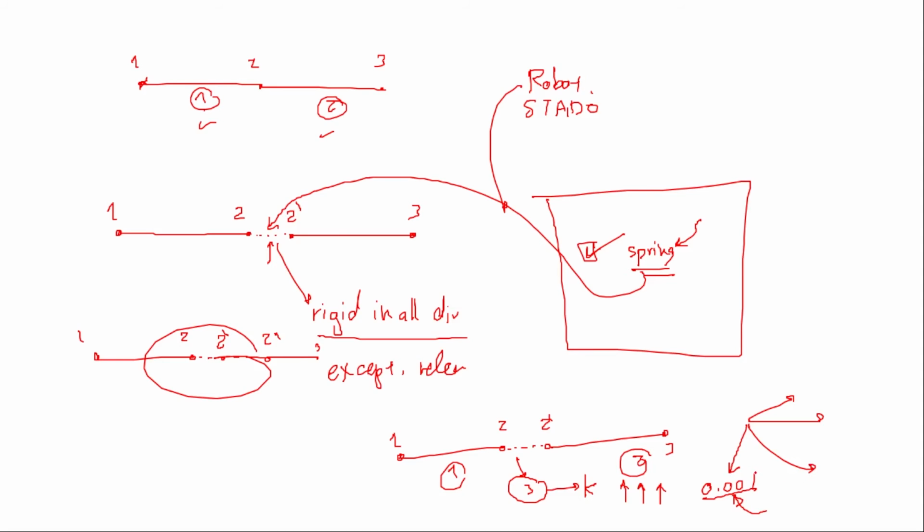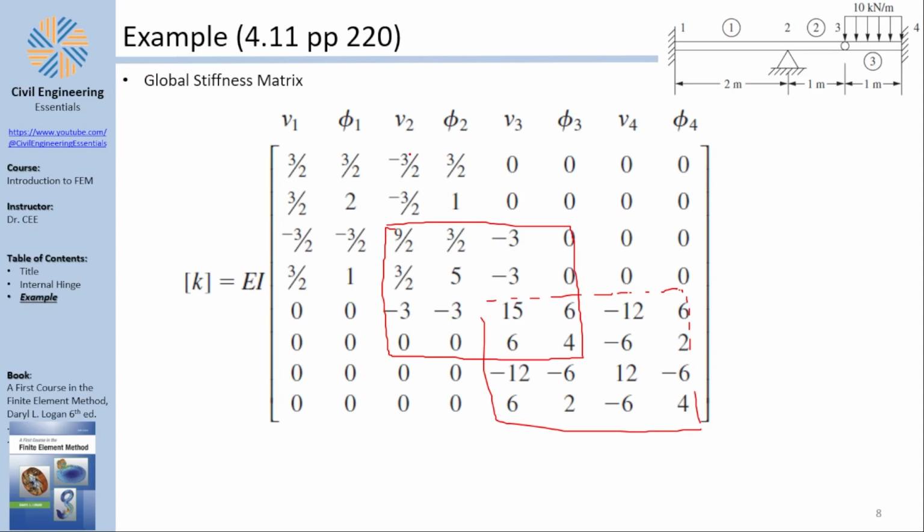This is really high level stuff, I know. Because of a small stiffness value, just besides a huge stiffness value of 1 million, this would cause numerical problems and issues, and we can solve them partially by using something called preconditioning algorithms and even solution algorithms like the skyline. Now, this is really high-level stuff. I tell you, like I know this because I have done this. So that's how softwares perform internal releases.